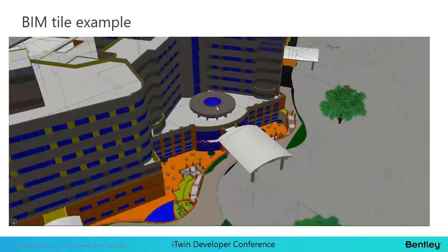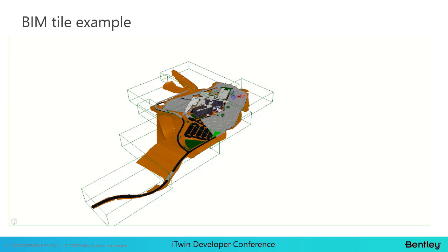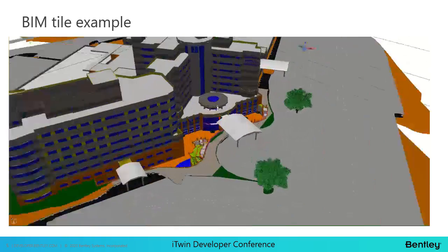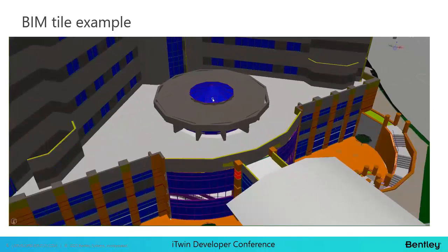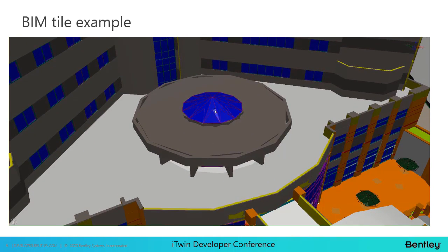Again, I'll zoom out. When I zoom out, it goes back to the large, low resolution tiles. Now, as a matter of demonstration here, I'm going to use a key-in to freeze the tiles. And then let's go back in, zoom in, and see what those tiles look like. Now remember, this is a frozen view of the low resolution tiles for the fitted view.